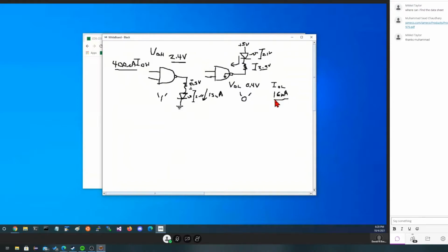I'll give you a little bit of a clue that if we do our resistor thing where we're 10%, but we're 10% the wrong direction, we may have enough, we may not. So this is right on the edge of being able to be used. So neither of these two designs at this point are reasonable to use. So if we needed to turn on an LED to reflect the status of a TTL output, we don't really have a good option. There's nothing in hooking an LED up to this that's going to allow us to do that easily.